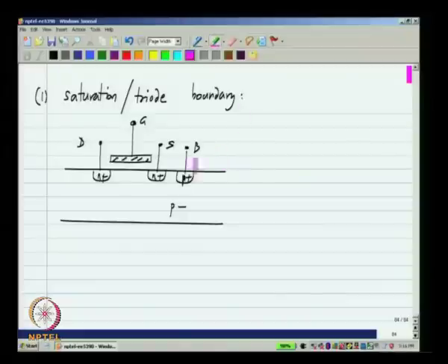Okay. You know that if you tie drain and source together so that these two are at the same potential, and then you go on increasing the potential of the gate, what happens is below the gate you will form an inversion layer, and around here you will have a depletion layer, okay, with fixed charges. And in this you will have the inversion layer, and the inversion layer is what is responsible for conduction of current in the MOS transistor.